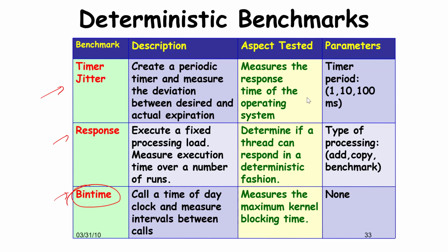So the timer period will be between 1, 10, and 100 milliseconds for such tests. But that will essentially give you an idea of whether the operating system is free enough to take up a timer interrupt immediately, or is it busy doing something else? So this will tell you, is it overloaded, or for a normal load is it being able to process it or not.